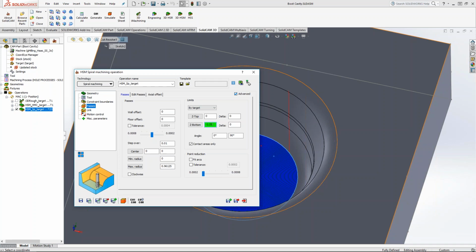And when you're doing cavities and cores, again, like I said in the beginning, surface finish is critical. Especially if you're doing something with clear plastic, those are highly polished, and you don't need any swirl. A swirl would basically be considered a gouge, and it's not from the tool, but from a chip dragging across and scratching a deep scratch in the bottom.